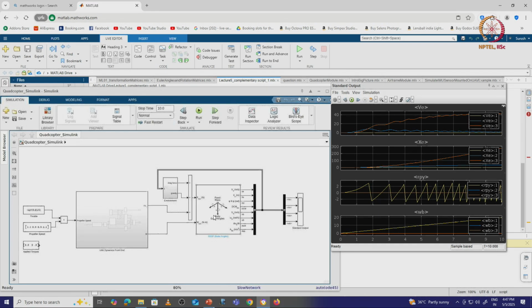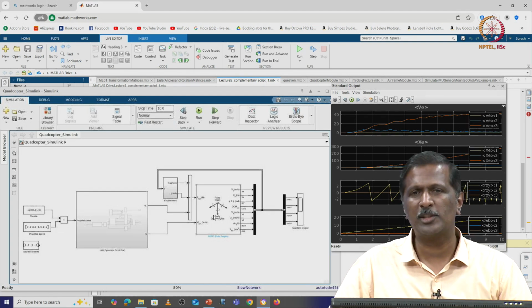Then you have external sensors. You can have a camera, which could be monocular, or a binocular camera which can get the depth, or you can have a LiDAR or a radar which observes the environment in which the drone is moving. For example, if you want to avoid collision with some static or moving object, we need these external sensors. In addition, we can also measure the wind disturbances, so the control becomes much more realistic.